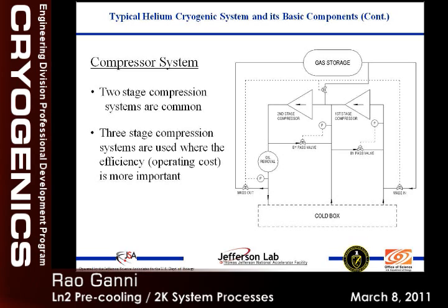From the enthalpy level, they're equal, but what we do is we take this high entropy gas, we compress it, we reject the heat into the cooling tower, and we reduce the entropy. By reducing the entropy, we increase the availability in the fluid, which becomes useful in the turbines and in processing your load. If you look at energy level, there's very little difference here. They all have equivalent enthalpy level. But the availability level, that's what provides the useful refrigeration.